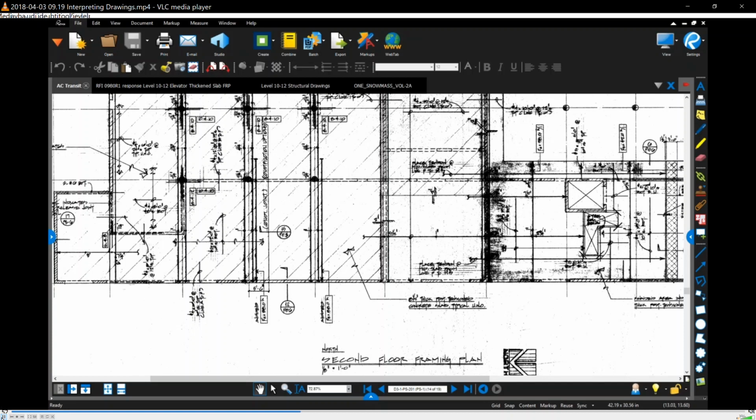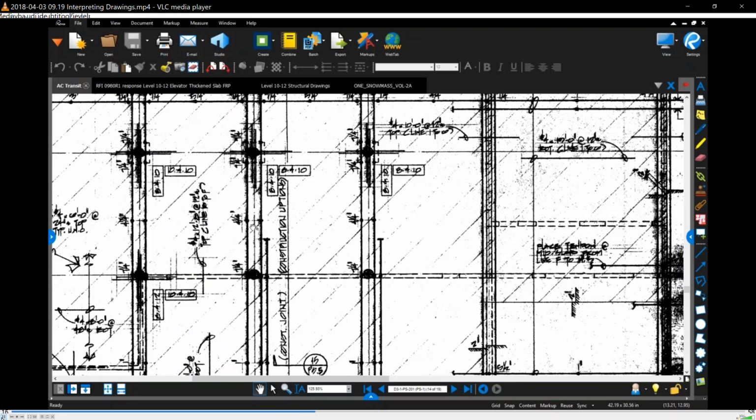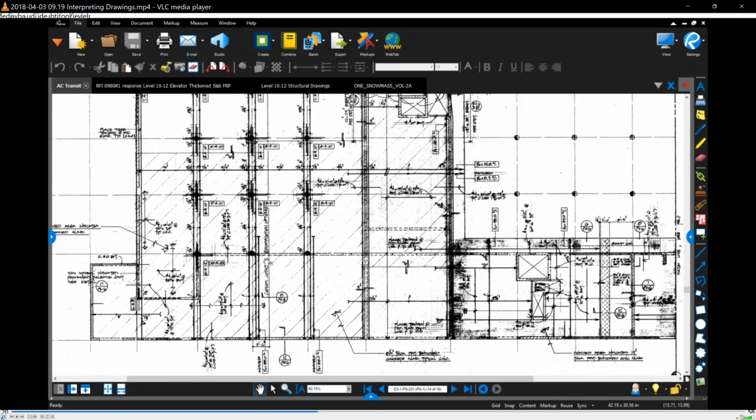When they did the design, they needed some additional strength because this last bay is so long, and you're not getting the full profile. Your tendon profile is at mid-height of slab here and at the top point here. Whereas here, while the span is shorter, you're getting a high point tendon here and a high point tendon here, and you can do this all the way to the lowest point if you want. You can see this is only at 4 1/4, so it didn't need as much uplift there.